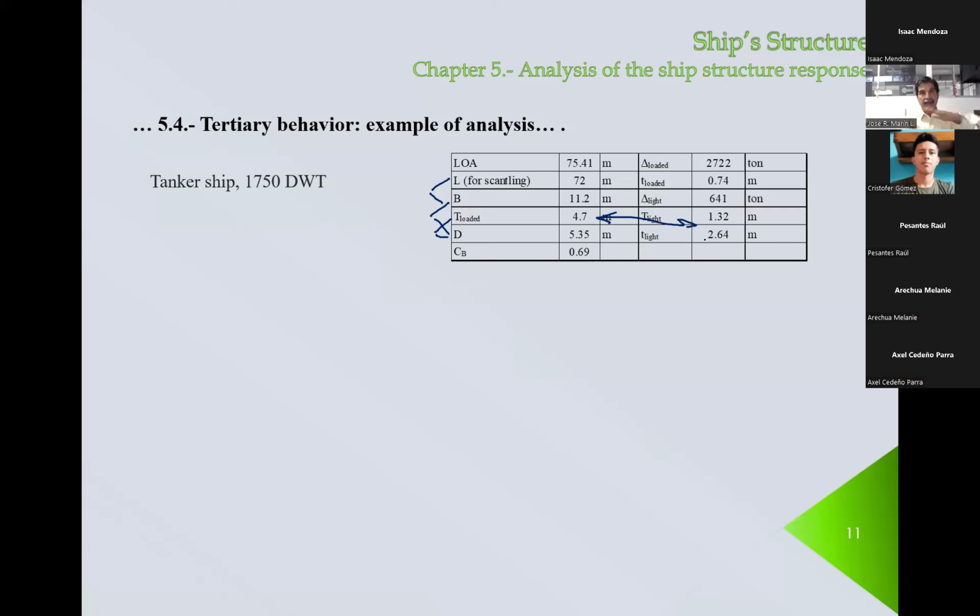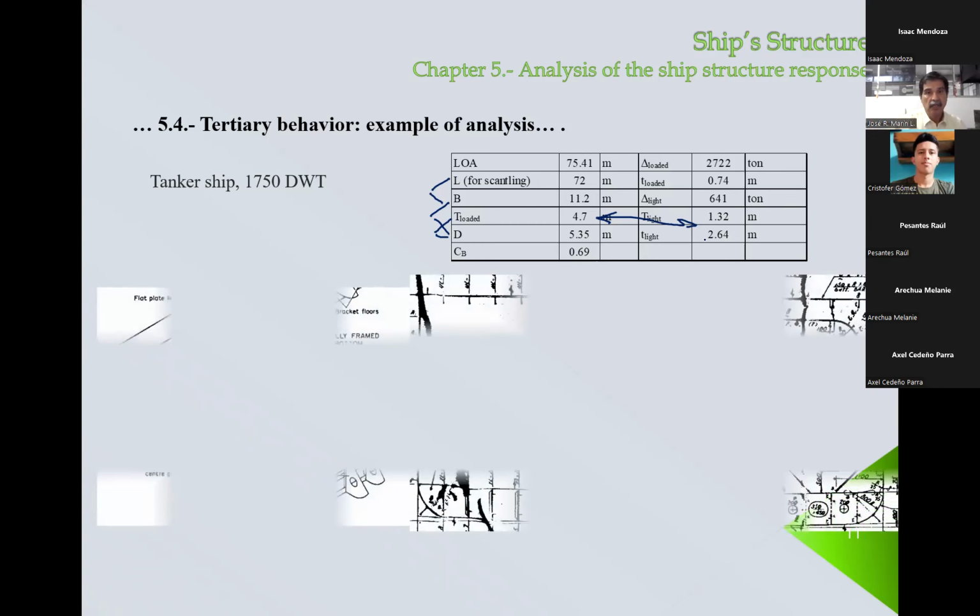And when you are inclined, the baseline is like that, and the horizontal is like that. So equilibrium means that the weight is here and the buoyancy center is here, but the distance in the x direction, they do not coincide. So be careful when you have to do a stability analysis of this type of ships.